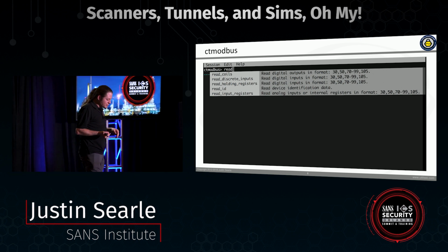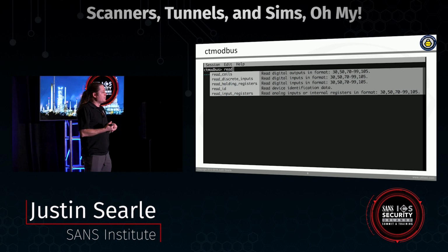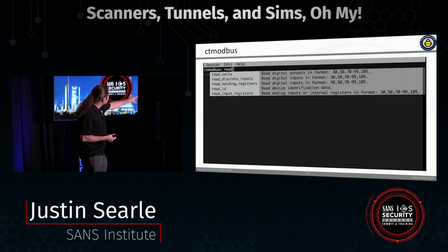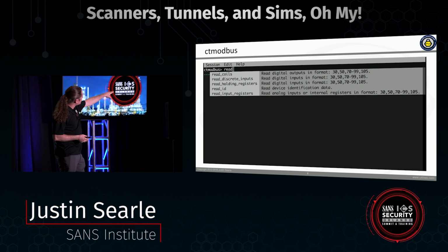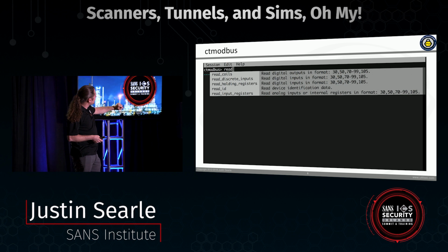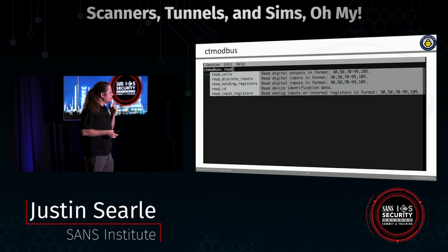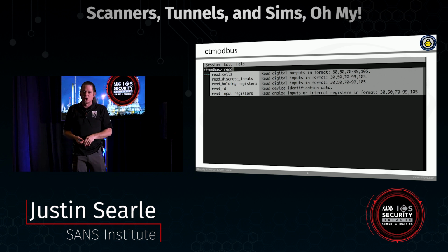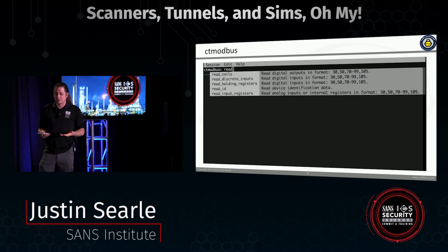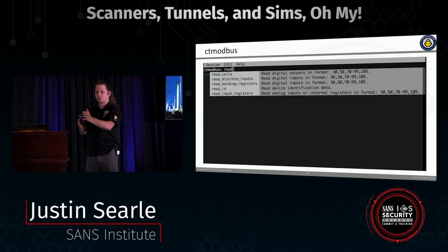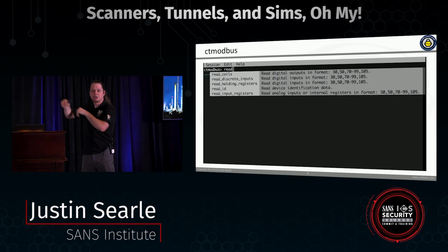When it comes down to flexible formats, right? I mentioned I need to have flexible formats at the input that's not very limited like a lot of the engineering tools. If you look at any of these examples, for the read coils or read discrete inputs, look on the far right-hand side for the format that's present. Comma-separated ranges is what I like calling that. We specify very specifically, I want this register, this register, this range of registers, this register, right?